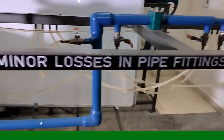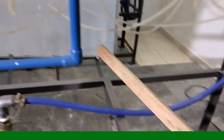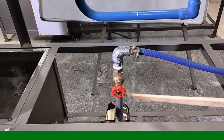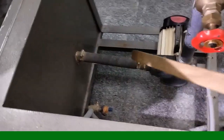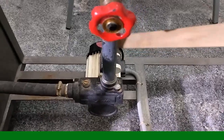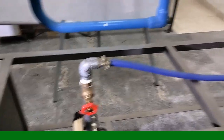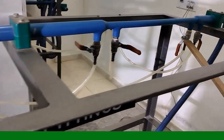By rotating this control valve, which is also called the delivery valve. This is the pump, this is the suction pipe, this is the delivery pipe. So this is the delivery pipe for the pump. That's why we call it the delivery valve, and also we control the flow with it, that's why we call it the control valve. And these pressure tapping valves we call ball valves or simply pressure tapping valves. Just different names are given according to the valves.